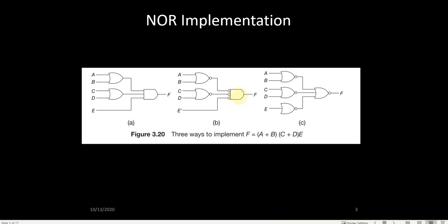So this is an AND gate. Obviously, if you put one more bubble only, then this will become NOR, but this bubble doesn't have a gate to cancel. So this E has become E bar here, right? So we have put an E bar here. In the next stage, we have replaced this all-input-inverted AND with a NOR gate, and this E bar we have again reverted back to E and put a NOR gate here. This single line indicates the 2 input lines are shorted with each other. Is it okay? Anybody has got a doubt with this kind of simplification?